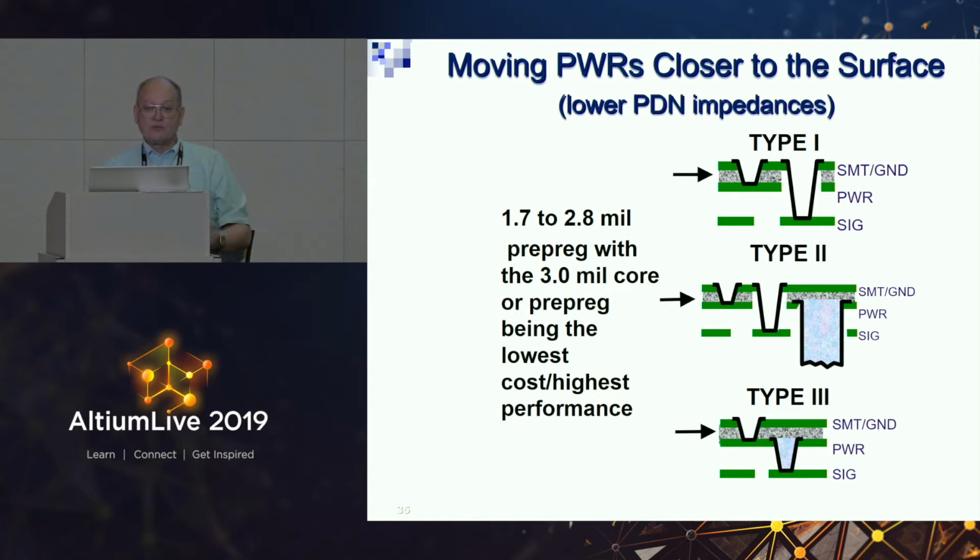So this is one reason why you have your land pattern on the surface and your ground. Forget about any traces on the surface. Put the traces down inside the board. And put the power, and also why you can now use multiple split power planes. And I'll show you later here that they no longer become planes. They become coplanar RF distribution networks.